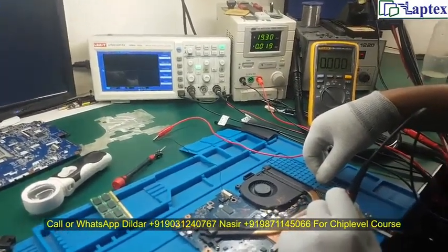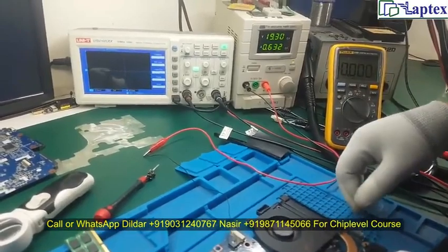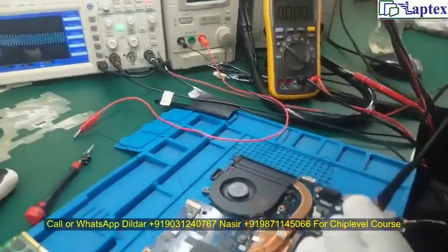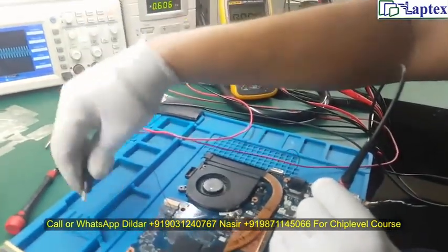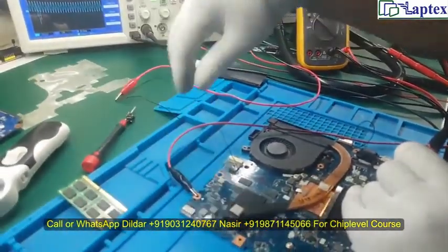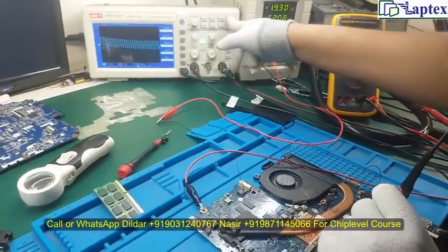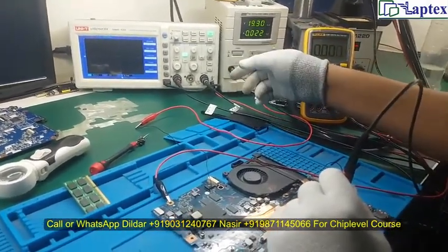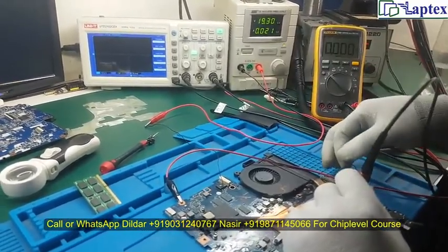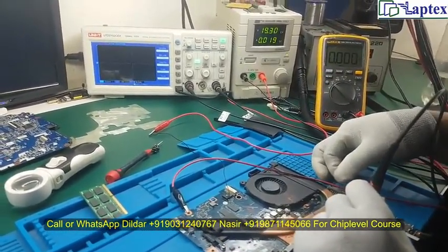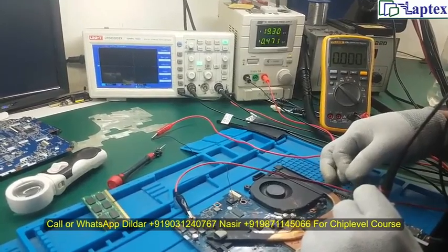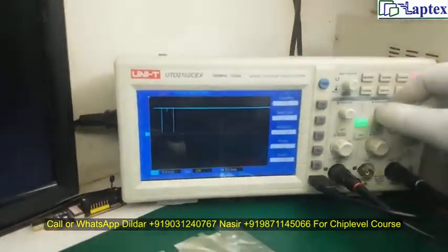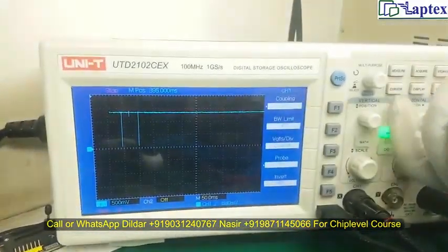So now you can see my DSO is still in capture mode. Something has gone wrong, and what was wrong? I forgot to use the ground reference. Now let me set it back. You just have to come out by pressing the run button. I am keeping the probe on pin number 30. Now I have adjusted my on/off switch by connecting this jumper wire. Now something happened over there. Let me adjust it this way.